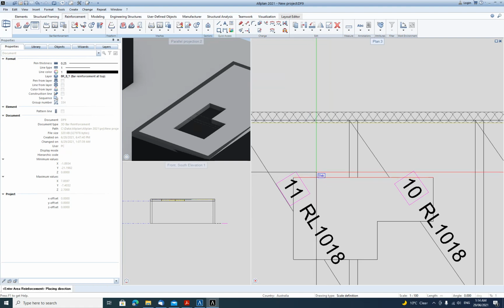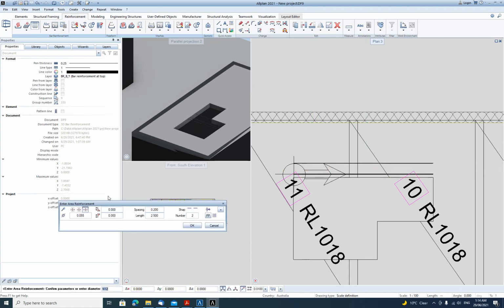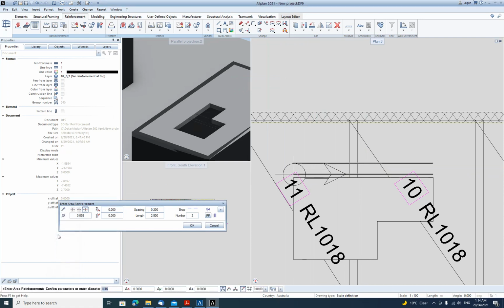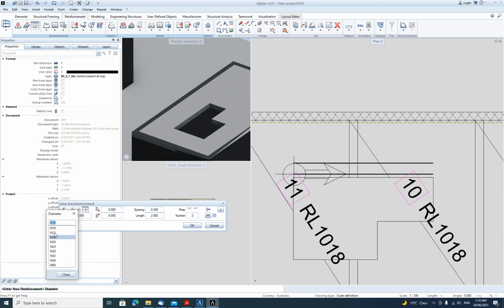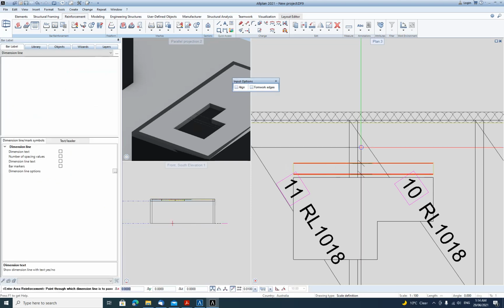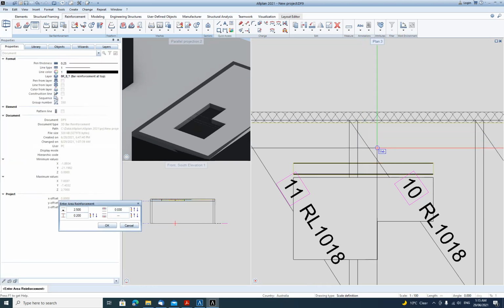By selecting slab opening and the size. In here I can already see I have different names than before, because this is now changed to Australian standard cross-section catalog. Confirm and press.